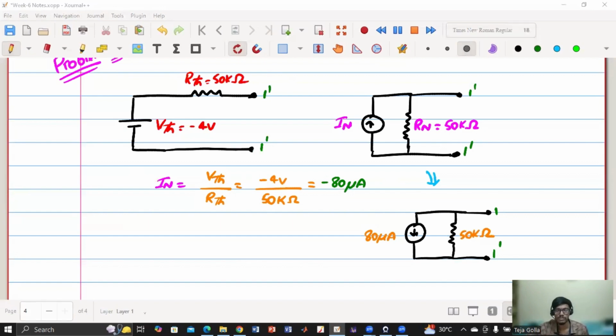It's just source transformation. Yes, you can say that. I have not used that word because sir has not taught it in the course, so if I use it, some people might get confused, but Roshan, you are right. It is just a source transformation. Kindly check the voltage polarity. Voltage will be plus on the top and current is a source, not a sink, so it will be from bottom to top. Voltage could be negative, current could be negative. It means it is the other way around with the positive magnitude, but kindly follow this convention.